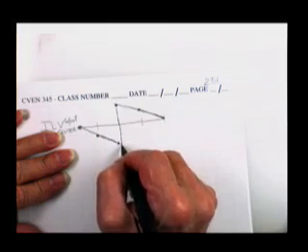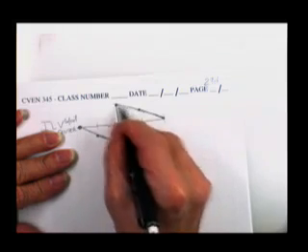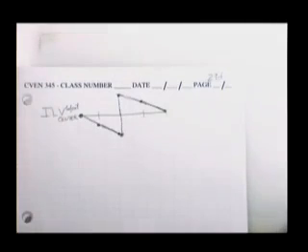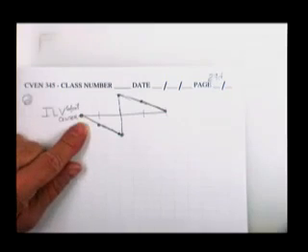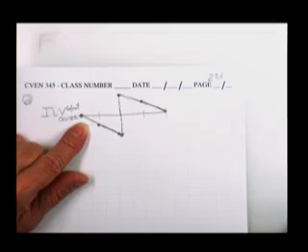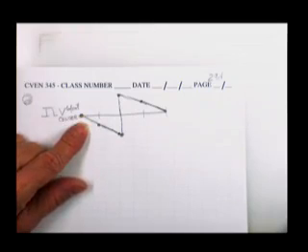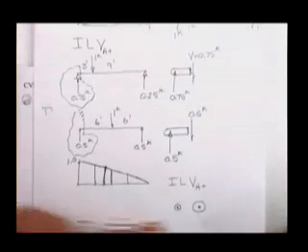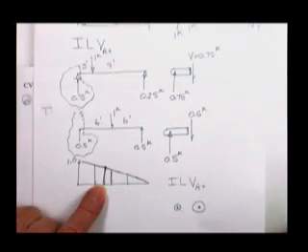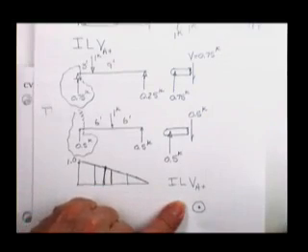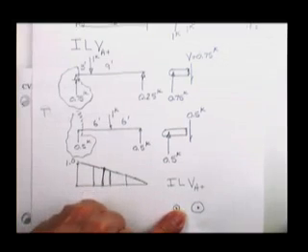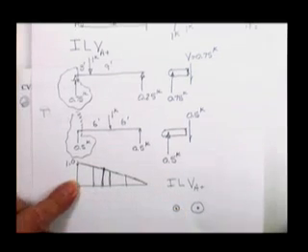Who needs to know the influence line for the shear at the middle? Well, you do, because the boss is going to come by and say, Joe, go tell me what steel section, how many steel plates I need to resist the shear at the left end. And he'll be drawing this influence line right here, and he'll know where to put the wheels and which direction to go, and he'll be able to calculate the biggest shear possible from that truck, and he'll be able to design the beam.